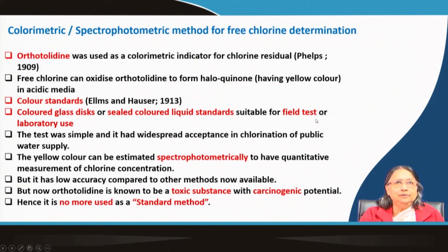These are very useful for field tests, because in the field you cannot carry the instrument, only the test kit. It is very good to carry, a small kit: you just go there, mix it on the spot, and then compare it with the disc or with the standards. It is easy. But it can also be estimated spectrophotometrically to have a quantitative measurement of chlorine concentration.